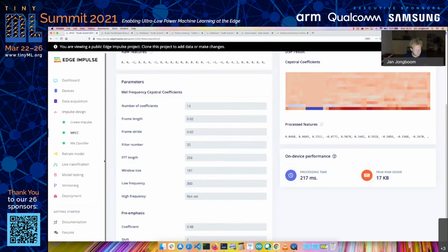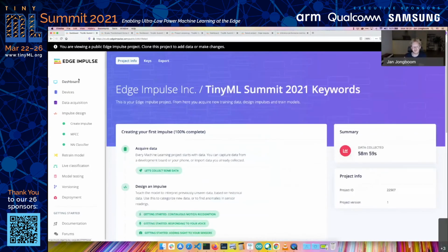Can I combine vibration output along with the audio data for the neural network? Yeah, I think it's a typical sensor fusion problem. We do this in, there was an ECG question earlier. For a customer, they do ECG with PPG data, with ECG data mixed with some other things to do sensor fusion. That's something you can do as well for audio and vibration. The only thing is there's a large discrepancy in the frequency typically between these. So you might need to think a bit about that. Dan, do you know?